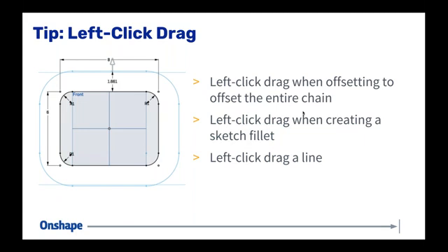Again, left click, and you have a line. But what's also not quite as popular, but very productive, is a left click drag line, right? So instead of two left clicks, you left click drag and let go, and you have a line. Now, the benefit of this approach is that by default, it does not assume that you want to continue creating lines. So there's not that additional click, escape, out of the line feature that you would normally have if you're just using the two-click method, right?